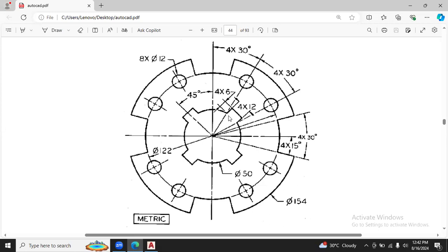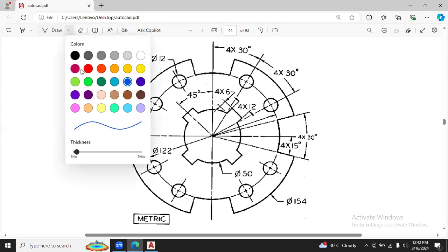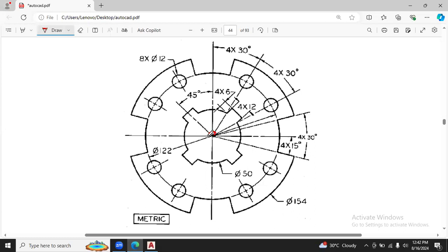First, you need to properly analyze what you are going to perform. So, in this model, there are multiple circles with the same center point. I think we should prefer the center point right here. At this point, we will take 0, comma 0, and then we have to draw this inner circle first, which is provided with a diameter of 50.